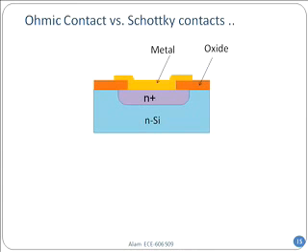So let me talk about a few things about these metal semiconductor junctions. Metal semiconductor junctions are everywhere. If you have a metal, let's say even when you talk about a PN junction, or any junction whatsoever, you always have to connect at the end of the day with metal, right? And if you are connecting with metal, there's a wiring. If you want to wire things up, then you will always have a barrier. Now the question is, if you have that barrier, then how is current going to flow? You don't want that anytime you put a metal down, there is a barrier, because then current may not flow unless you apply a bias.